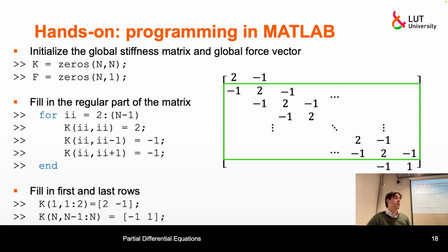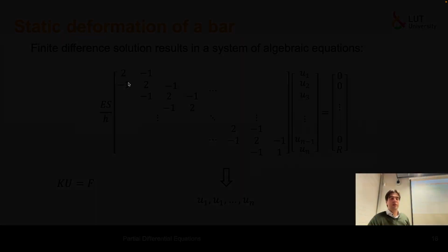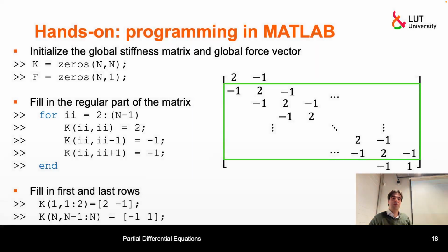It's a very possible situation. And in that case, it really matters how you deal with this set of equations afterwards, this Ku equal to F. You would like to have this matrix with as narrow a band as possible to solve this problem effectively in reasonable time using the resources of your available hardware.